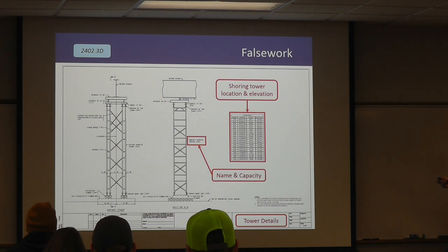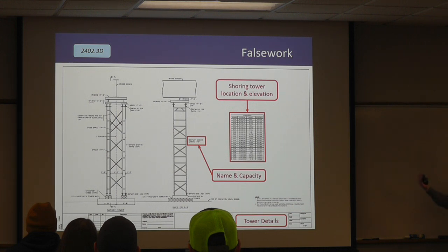You're going to have elevations. This is really important. Again, not for you to check, but to see that somebody has done the work, right? Because we had an instance where the contractor came out and they had the elevations. I think they were correct. Nobody ever checked that it was installed to those elevations, and it was 6 inches low. So when they went to land the girder, it was stiff enough that it never landed, right? It just held itself up. It's pretty hard to go on to the next phase of your erection sequence when you're depending on the girder being supported like that. So the contractor had to stop and figure out how to shim everything up 6 inches, right? Again, that's their onus, but be aware of it, right?